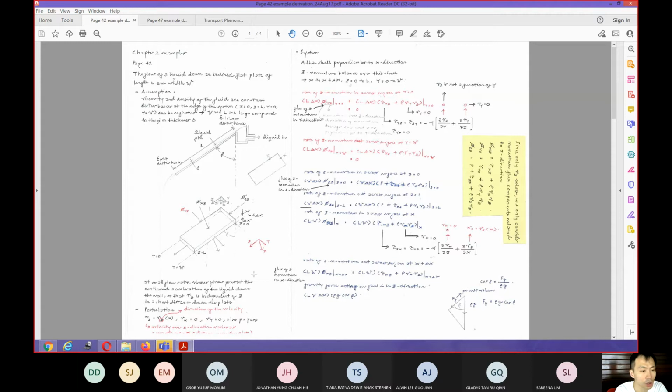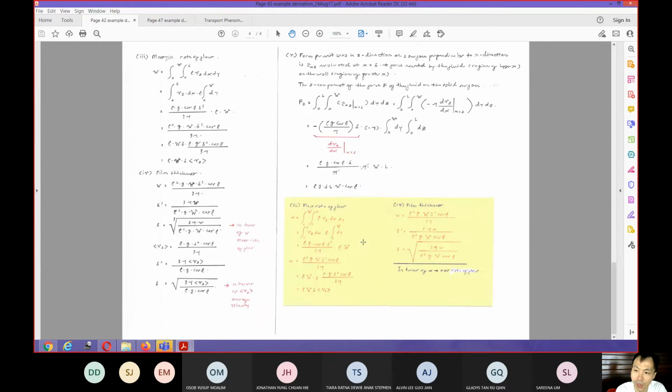Okay, so in your unit operations, if you want to get the film thickness of your particular system, if you can find out the viscosity, you can calculate the mass rate of flow, for example, and you can get the density, you can get the gravity easily, and then for a particular plate or film width, for example, and then the angle, then you can get the film thickness.